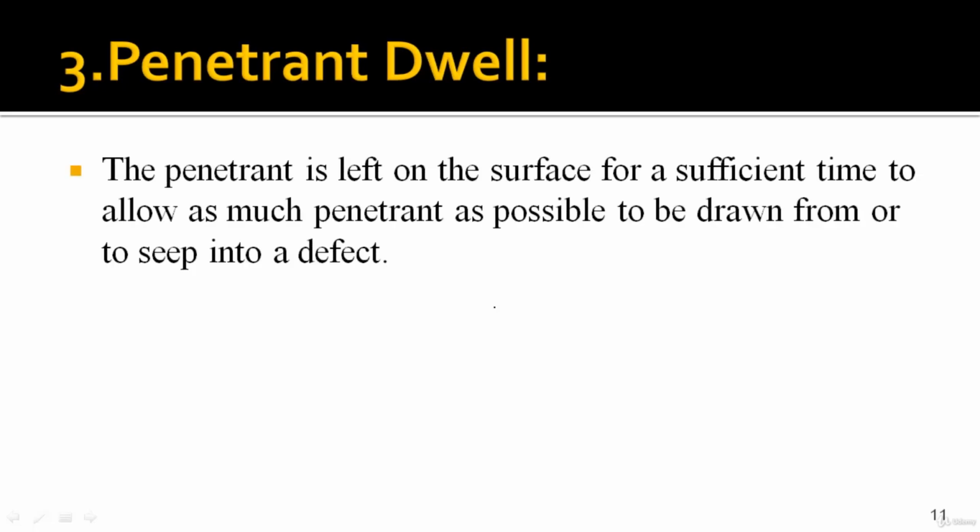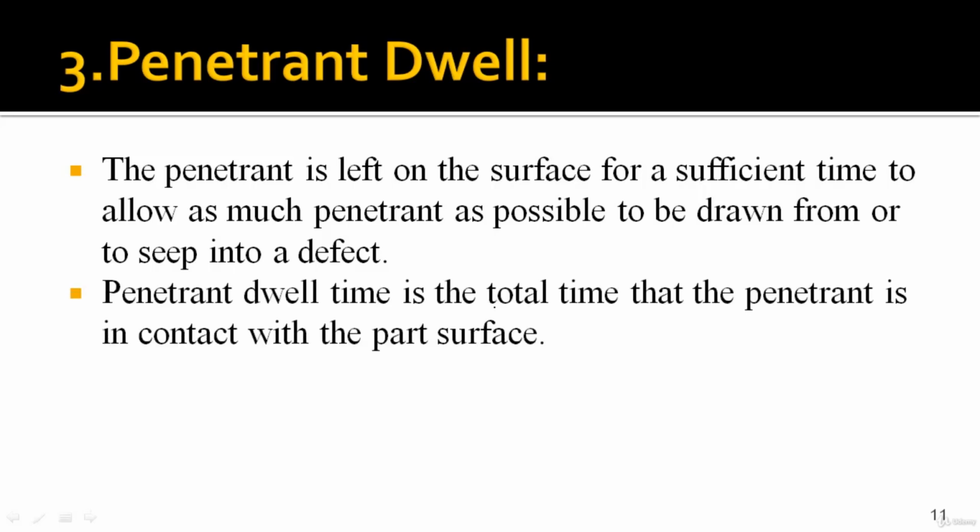After applying the penetrant, you have to wait for some time. The penetrant is left on the surface for a sufficient time to allow as much penetrant as possible to be drawn from the surface into a defect. We have to leave it for some time. Penetrant dwell time is the total time that the penetrant is in contact with the part surface. You will see the dwell time many times. Dwell time is the ideal time where penetrant will be in contact with the part surface.